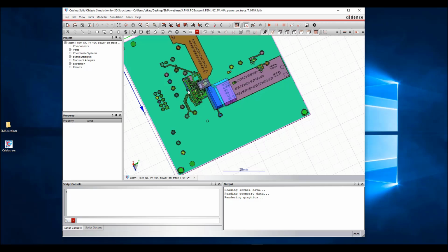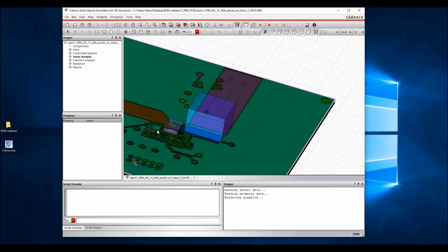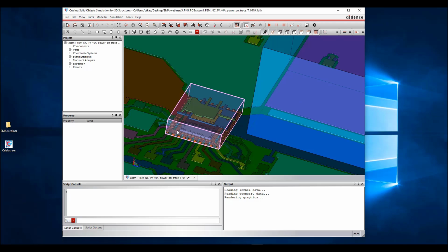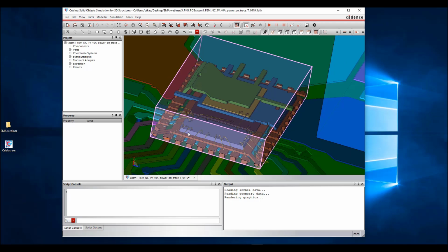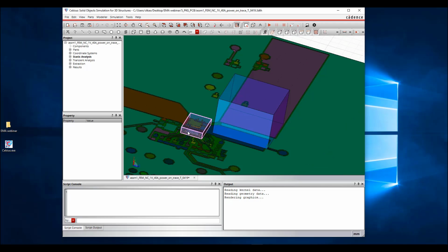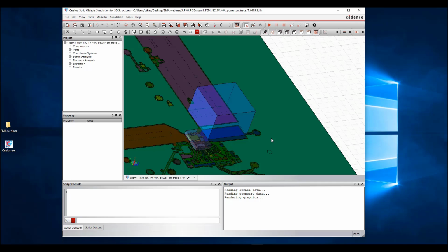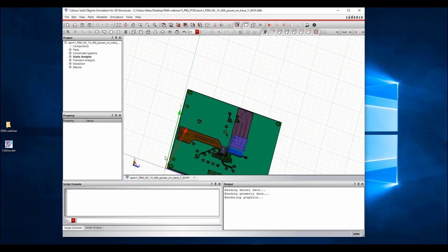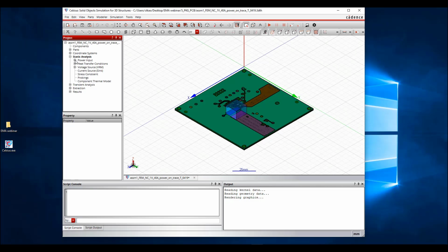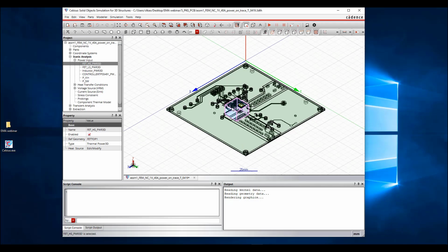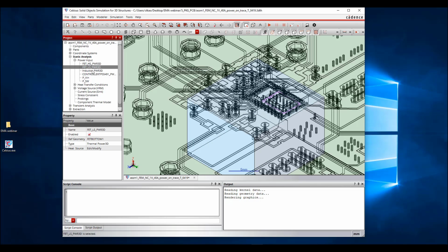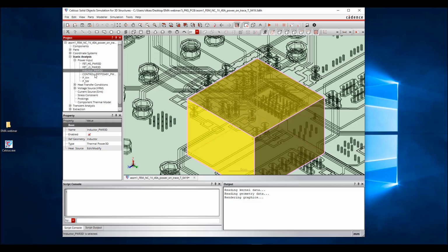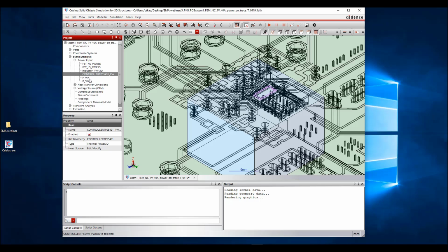You can see here we made some components transparent. You see some details inside. We have a bonding wire, bonding pad. We have two dies, and there's an inductor, and this is a customized PCB. So the detailed setup is just like we have shown you before, including material properties, boundary conditions, and power input. You have different powers. As I said, there are two powers. There could be a power in the inductor. They have a power in the controller and the current.